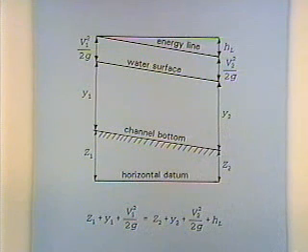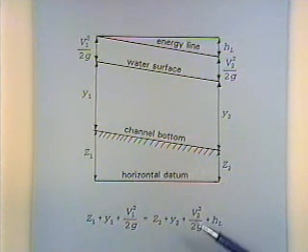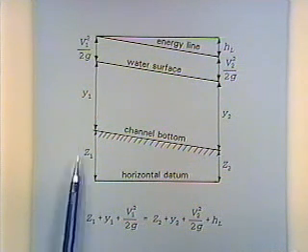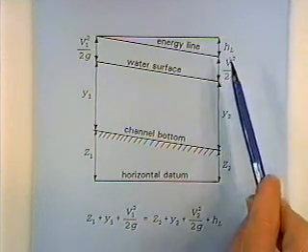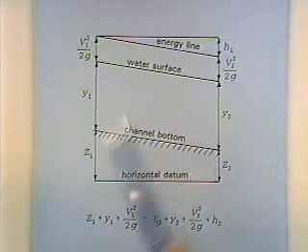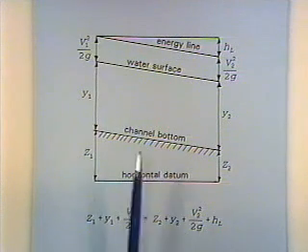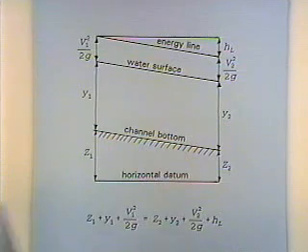The terms are defined, and this is a key diagram, of course, relating the different terms in the energy equation. Elevation head, depth, velocity head upstream; elevation head, depth, velocity head downstream, the difference being the head loss. Now we have uniform flow, which we don't anymore, but back last time when we did have uniform flow, the channel bottom, water surface, and the energy line were parallel.